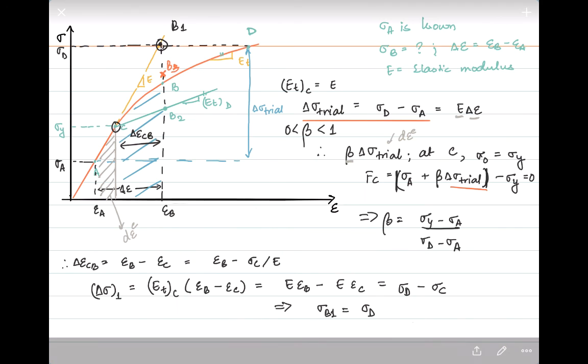Of course, the post-yielding part that has been shown to you here is part of the Euler two-step integration. So you can also find this in standard numerical analysis books. But this is just a flavor of how you can use incremental stress calculations to find out your curve for your material nonlinearity.